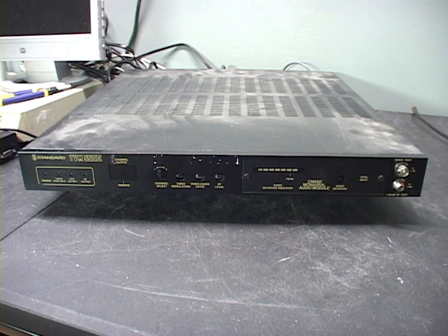From there, the cable head end demodulates that incoming RF signal back into the composite AV signal from whence it came, and remodulates it onto another channel, whatever channel that the cable company has decided that you deserve to be on.